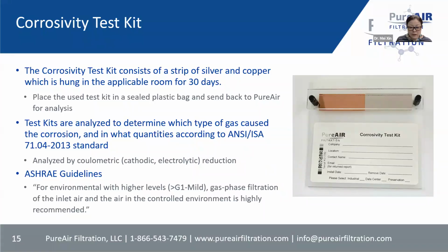For CTK tests, the duration may range over 30 days or maybe less than 30 days. With a removal date on the kits, we are going to report the corrosion ratings normalized to a 30-day, like 1 month, value in accordance with the method outlined in the ANSI standard. So keep in mind, we do need a removal date, so please remember to provide it.